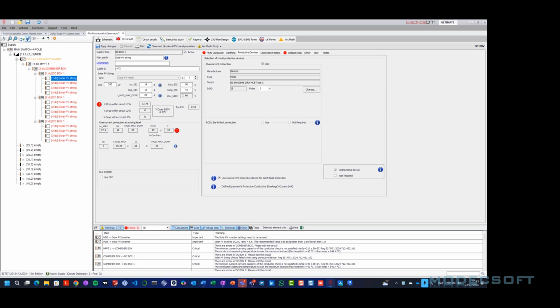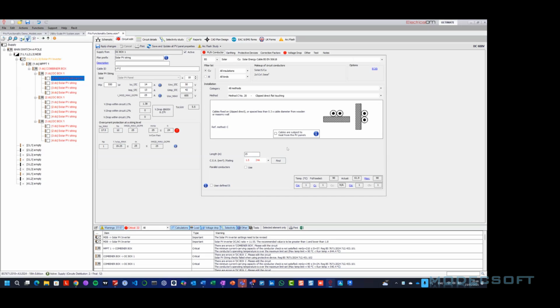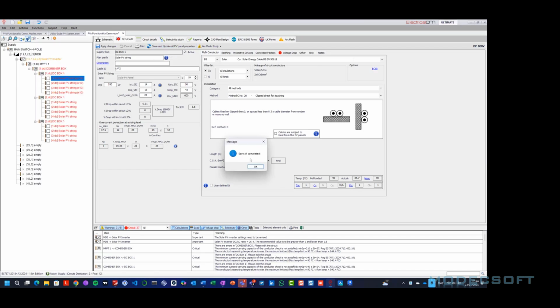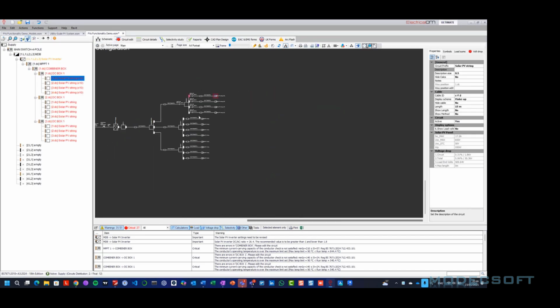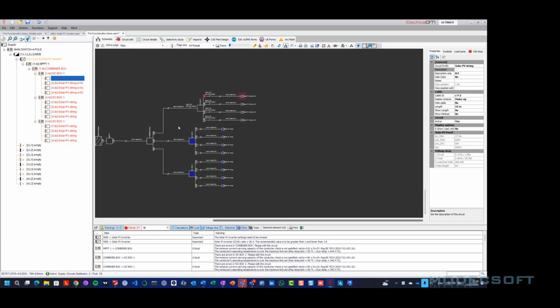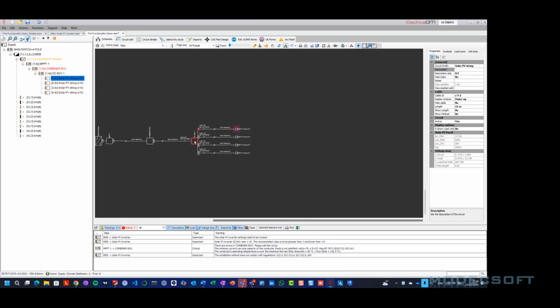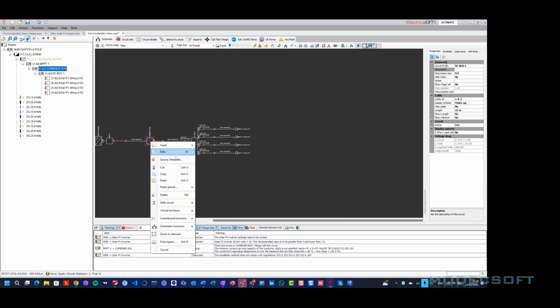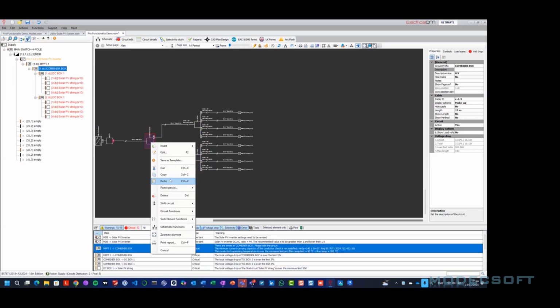We are getting a voltage drop warning because of the number of modules that we have. So I'm going to increase it to 10, apply the change, and adjust the cross-section area of our cable. I'm going to set it to 6 square millimeter and apply the change. So to quickly replicate that, I'm going to select save and update all PV properties. And I'm going to delete these 2 subarrays and replicate these again, so I don't have to define all these characteristics again from scratch.